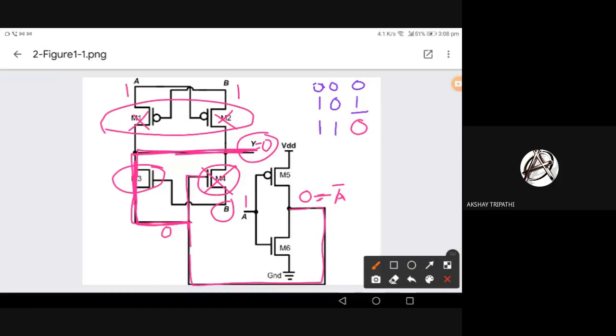If you understand, this field is digital VLSI design, where circuit designers, electronics engineers, and VLSI engineers are designing different kinds of gates, chips, or even processor parts. Basically, all microprocessors, any RAM or digital things are comprised of different types of individual gates: NOT gate, AND gate, OR gate. The fundamental gates are the NAND gate and NOR gate, right? And the NOT gate. Because using NAND and NOR gates, you can make all other gates.